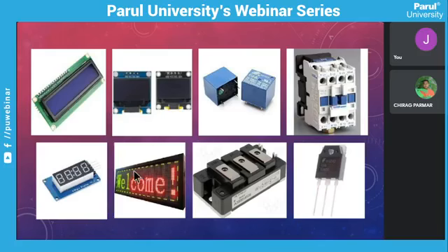It uses thousands of LEDs which are connected, and each and every one of those LEDs is lit by a particular pin. To light each and every one of these LEDs, a 1,000-pin controller is not required. In fact, whenever you see a scrolling display, it mainly incorporates shift registers. Each pin of each LED is connected to a pin of the shift register dedicated to each section of the dot matrix display, and the controller gives the data to the shift registers. The shift register which is mainly used here is the SN74HC595.